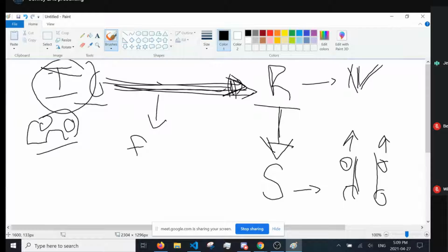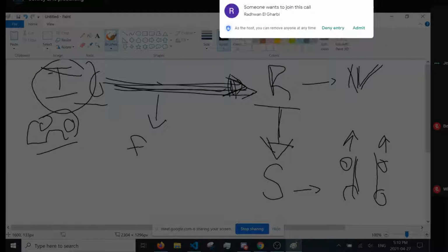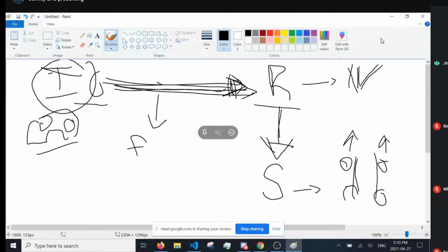That can be a problem because, first of all, when you're designing a system, you're often not thinking in terms of the actuation points, you're thinking in terms of different variables, right? So when I'm thinking about my robot drivetrain, and if I'm tracking a path, obviously what I'm keeping track of in my head is how fast the robot's actually moving, on its left side, on its right side, and I don't necessarily know what voltages are specifically being applied to the motor at any given point. And the problem with that is that in open loop control, you're not actually able to control the variables that you